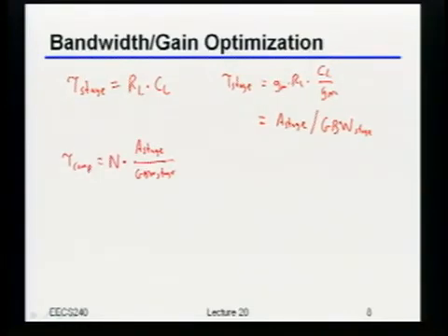All right, so now, since I made each one of these amplifiers the same, if I told you that I wanted a certain total gain, what would I set the gain of each stage to be? If I have n stages and I want a total gain, A total. Yeah, it's the nth root of the total gain, right? So the gain of each stage would just be the total gain to the 1 over n. Okay? Well, so why am I doing this?